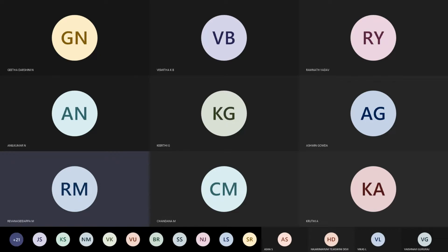It carries a reaction of 350 kilonewton from the suspended span together with a uniformly distributed load of 60 kilonewton per meter inclusive of its own weight. These are the loading conditions I have written in the figure. The beam is pre-stressed by 7 cables, each carrying a force of 1000 kilonewton. There are 7 number of cables, each carrying 1000 kilonewton.